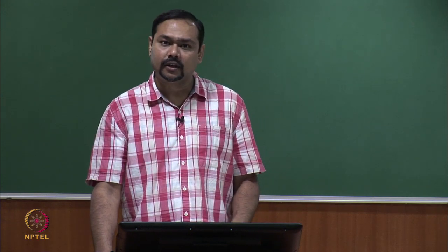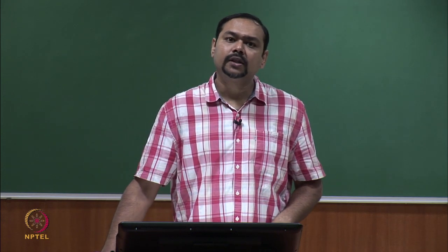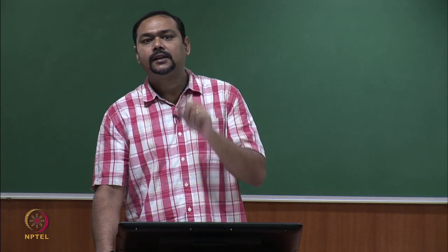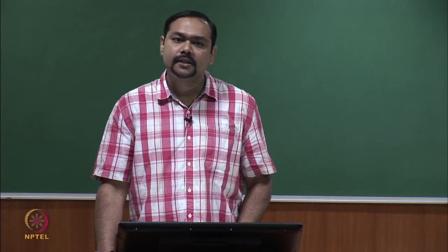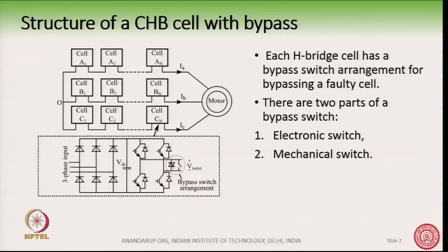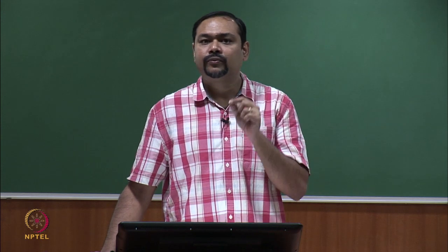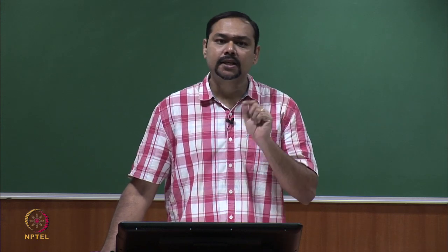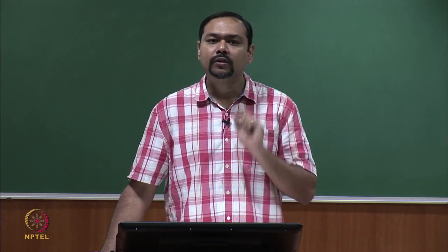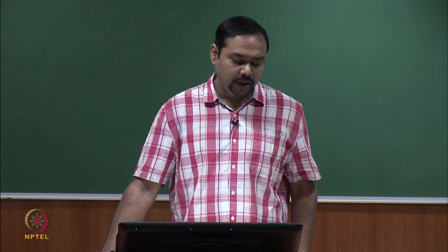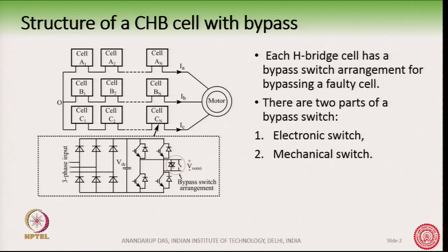But you do not want the whole converter to shut down because of failure of one single component inside one cell. For example, there can be a small fault in the gate driver board for one IGBT inside one cell.